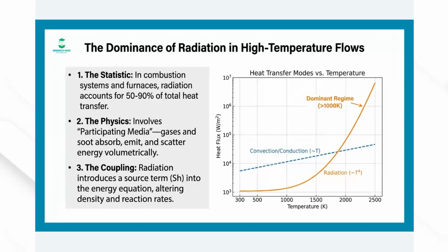So to put a number on this, in combustion systems or furnaces or battery fires, radiation essentially accounts for 50 to 90% of total heat transfer. If you are simulating a fire and you leave out radiation, you are effectively deleting half or more of the energy inside your system. Now, here is sort of a shift in thinking.